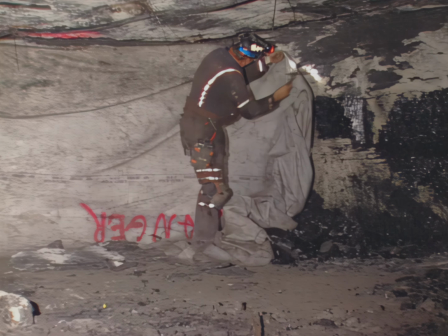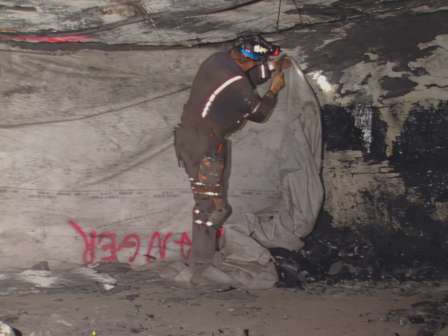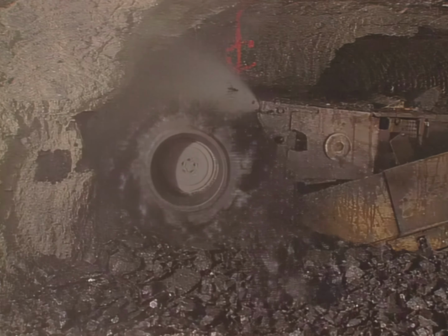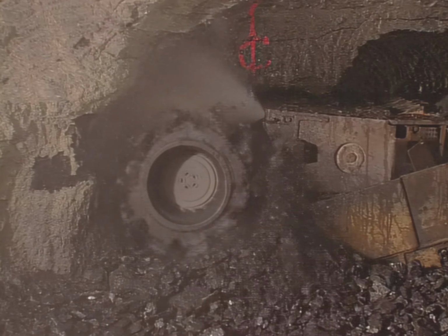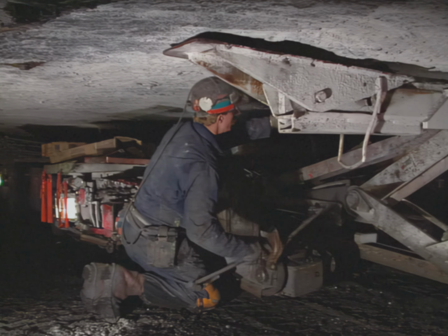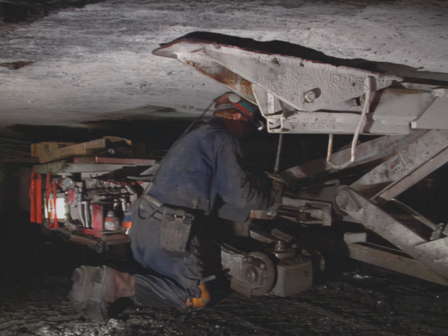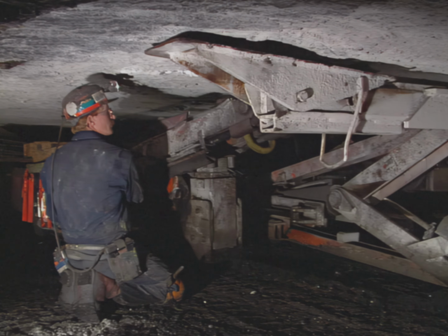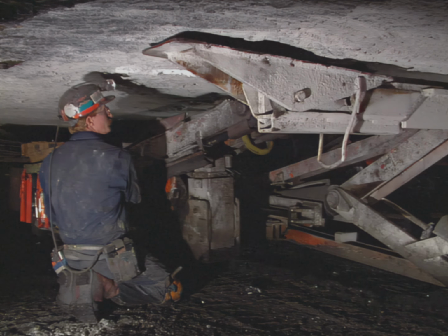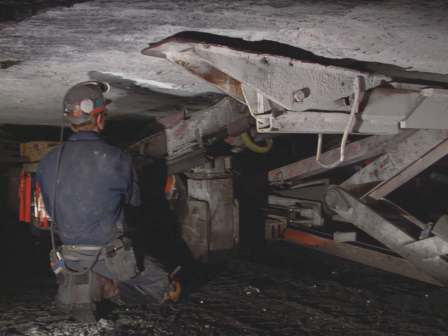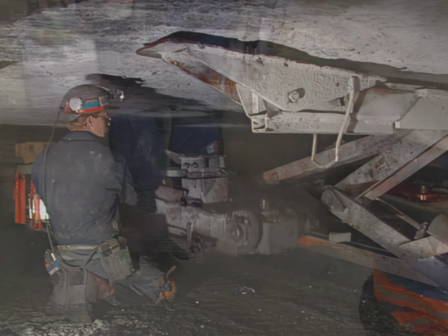Now, what does this mean to you? Well, every day you have to deal with changing geological conditions. Every cut of coal opens up unknown territory and reveals new potential hazards. Many mines are in coal reserves that in the past were avoided because of poor roof conditions. Mines are often deeper than they used to be, and they may have old works over or under them, which can place additional stress on the roof and ribs.